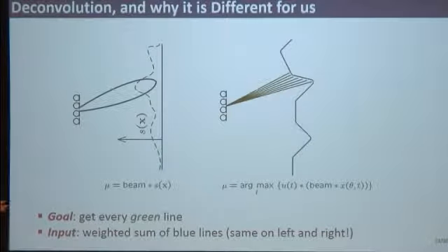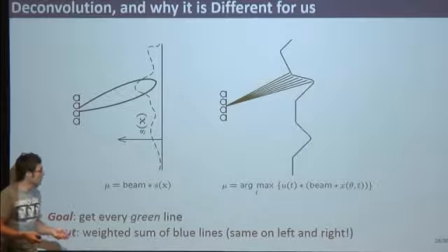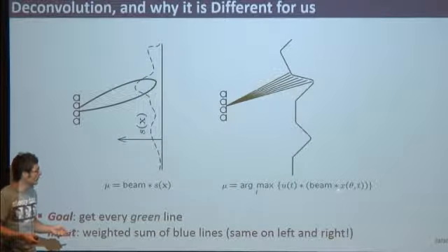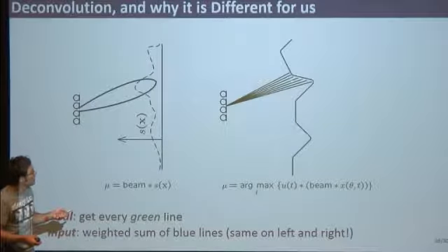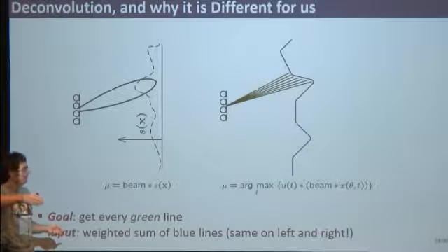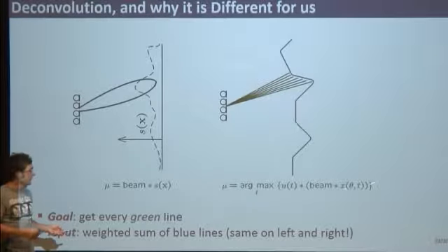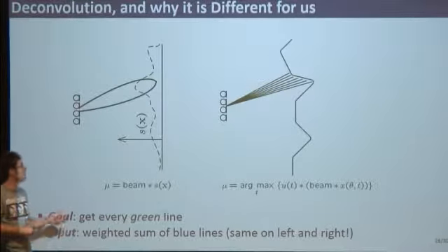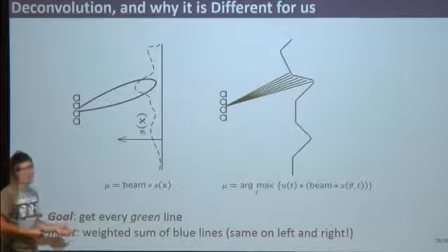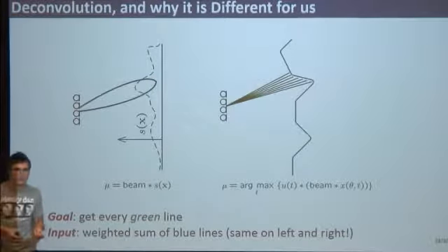So what is the image creation model that we have in depth imaging? Well, imagine that each small reflector here, each pixel, reflects a part of your sound back. And this reflected sound I call x of theta, for different directions theta, and t. So this is a function of time. Then again, this gets convolved with the beam shape, because you're not listening just to a particular pixel, you're actually listening to a weighted sum of pixels. So there's a convolution with the beam shape.